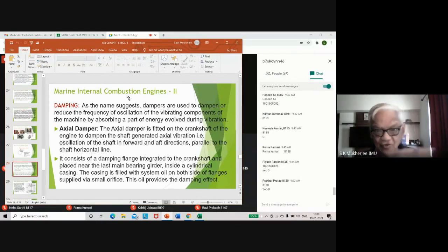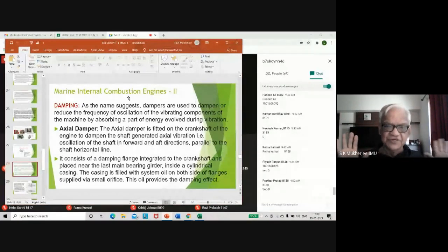So what are you going to do? You will immediately require to put a band-aid. What is a band-aid? A band-aid is a jubilee clamp with some rubber gasket, put it around with a band and tighten it. That is your temporary measure. You stop the leak. And also at the same time, you have to make some arrangement where the vibration has to be stopped.